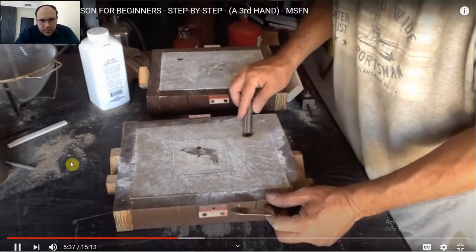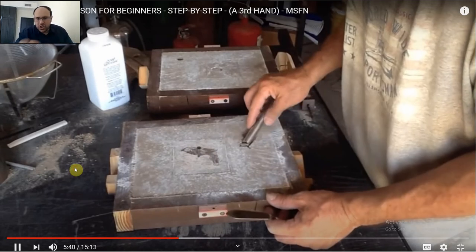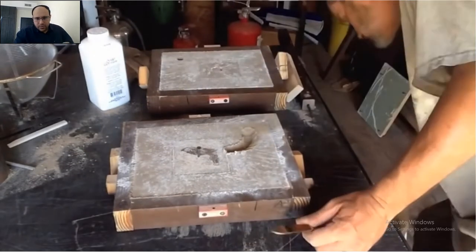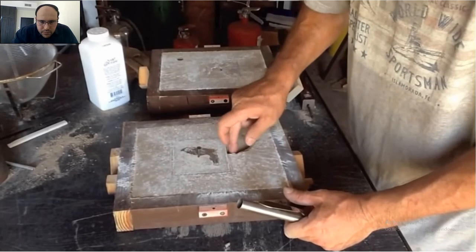And I'm preparing to go ahead and cut the gate. So this little small opening that he has made is just the base of this other opening, because you have the 2 halves, one on the top, the other at the bottom. Do you see this opening? This opening is where he's gonna pour the liquid. The liquid is gonna move down. Now he's making a runner or a gateway to fill into the cavity, because this thing should be empty after a while, right? So he's just forming this to run over to the pattern. And this is where the metal is going to flow to fill up my little void in the sand there.